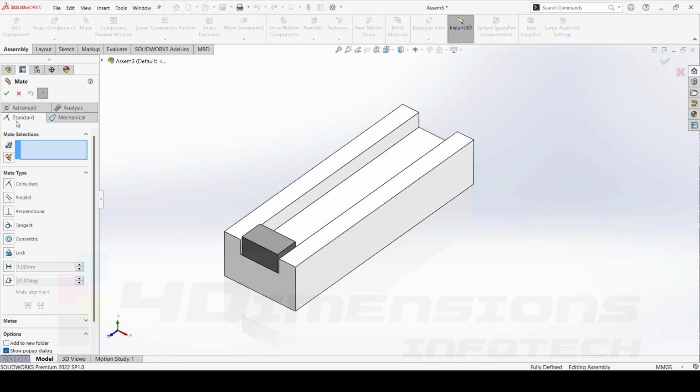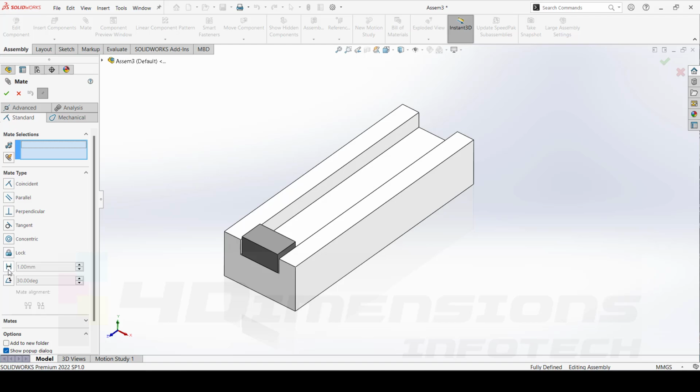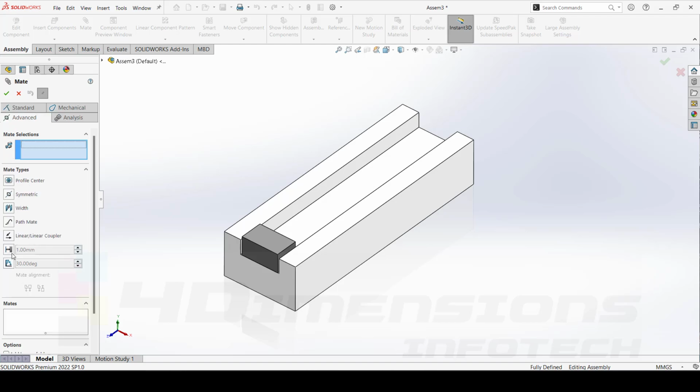Sometimes there is confusion, as we have standard mates where there is also a distance mate, but this distance mate is different from the limit distance mate of advanced mates. Here you need to apply only one distance, and in advanced mates you are going to apply maximum and minimum, two distances. So that's why limit distance mate is different from the standard mates distance mate. Say okay.